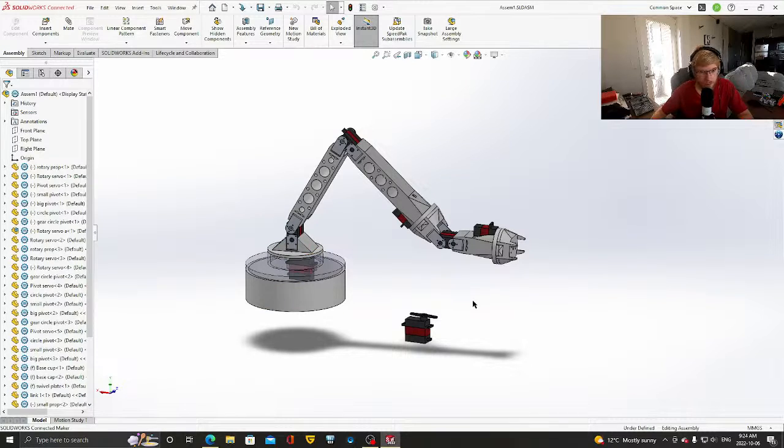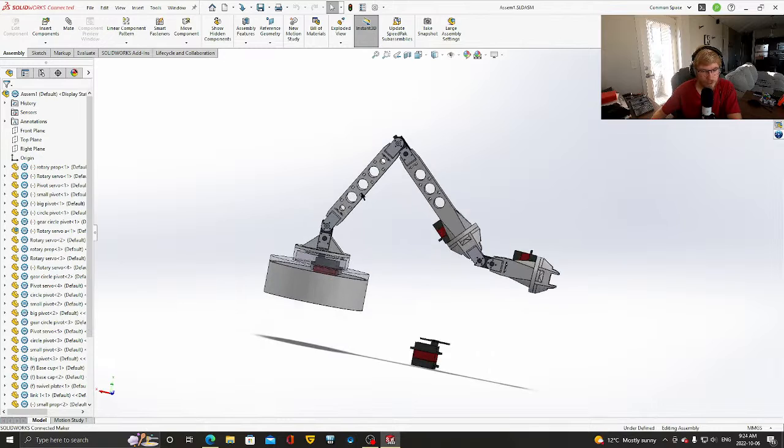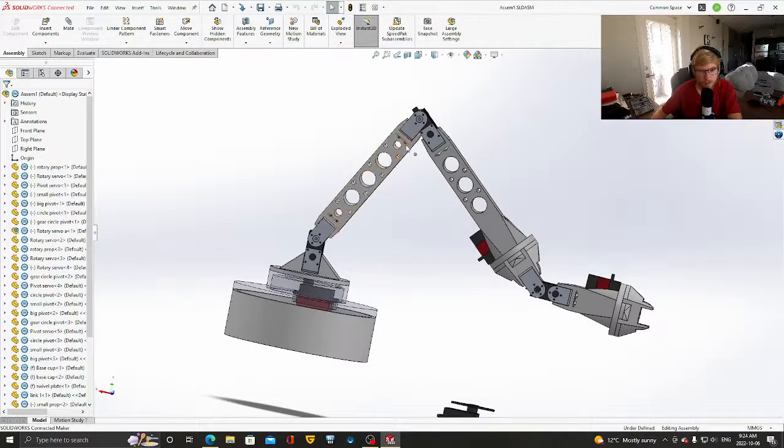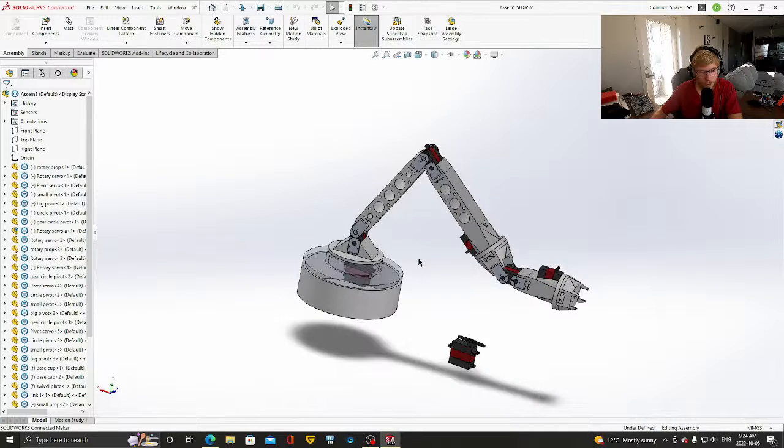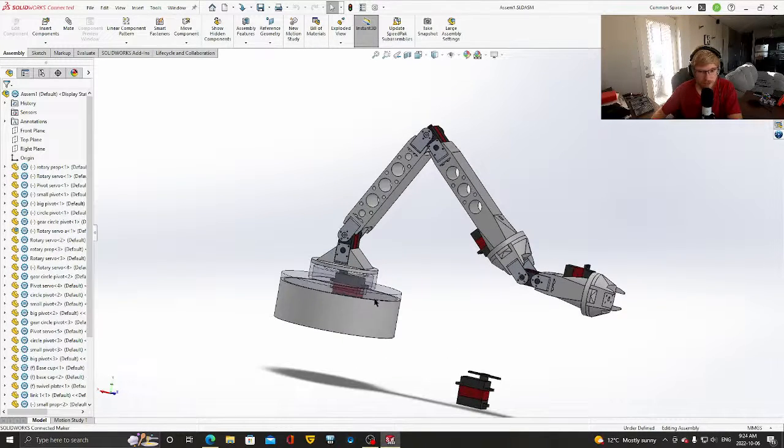And so I figured you can do the reverse kinematics, inverse kinematics, forward kinematics, all the different kinematics with the robotic arm. I'll do a bit of computational, not fluid dynamics, I guess, just finite element analysis, just to figure out the stresses in the components, to make sure none of those are going to break under load. We'll do a little bit of basic mechatronics, controlling all the little servos, do a bunch of modeling and control all those servos, use the kinematics to define what goes where.